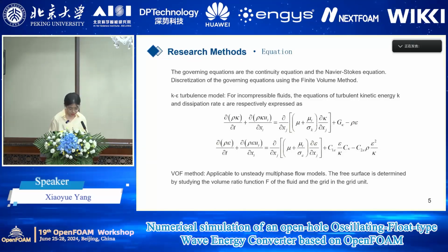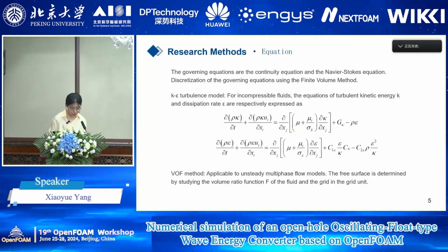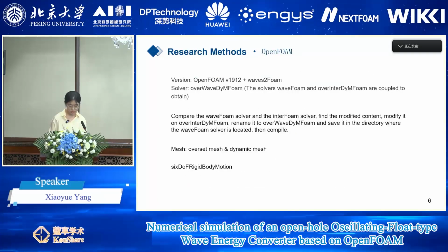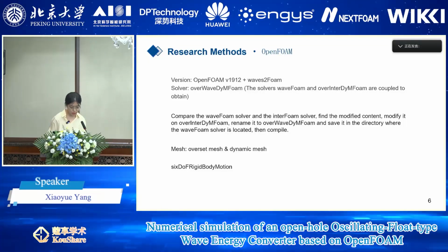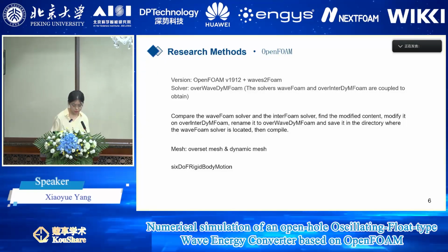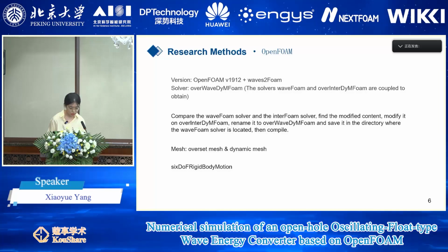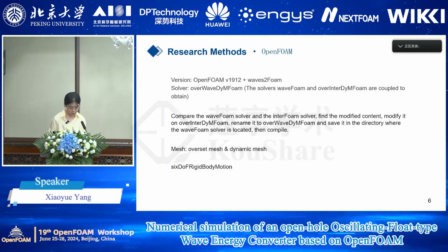For incompressible fluid, we choose the K-epsilon turbulence model, and we capture the free liquid surface by the VOF method. We used OpenFOAM V1912 and waves2Foam for simulation. Then we combined waves2Foam and overInterDyMFoam to get the solver overWaveDyMFoam.